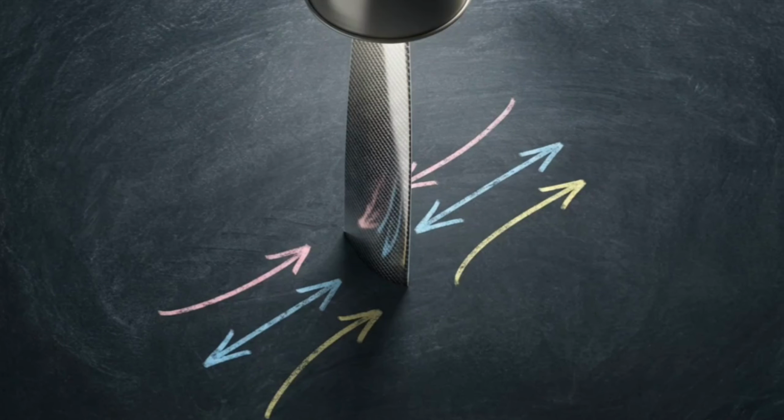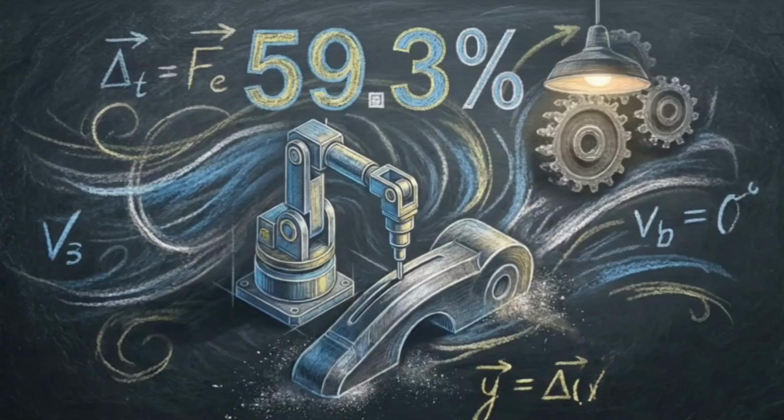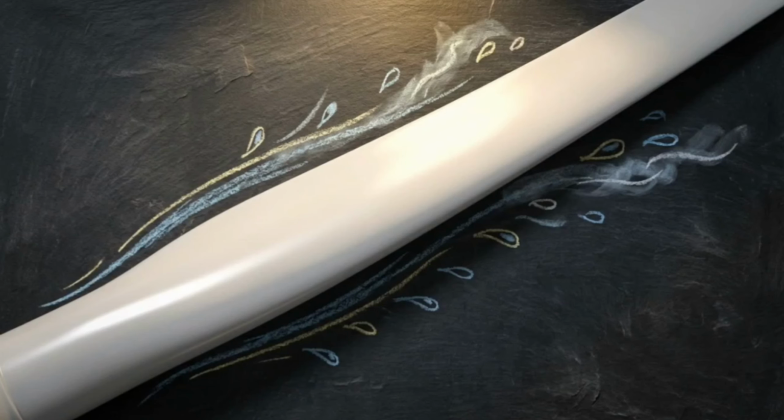No future material science or engineering breakthrough can bypass this thermodynamic limit. Betz's limit forms the unyielding ceiling of wind power. Modern engineering is a quest to design physical shapes that get as close to 59.3% as reality allows. To understand how we extract that energy, we have to move from the abstract column of air to the physical shape of the rotor blade interacting with it.